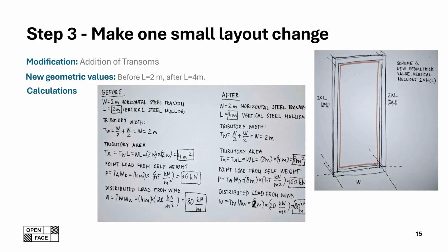But if the facade is connected with a typical pin type bracket connection, for example, which allows rotation, then the bracket does not carry bending moment. And in that case, any moment at the anchor would only come from geometric eccentricity between the through bolt and the anchors, not from the mullion bending itself.